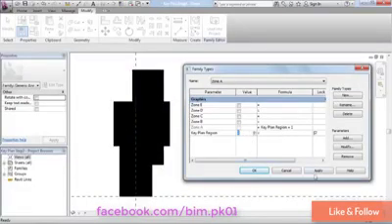So let's see how that works. Let's change this to 1 and click apply, and you'll notice that checks the box. If this value is anything else, right, 0, 2, 3, 4, it's not checked because that condition is false. So when it evaluates this condition, if it turns out to be true, it checks the box. If it turns out to be false, it doesn't check the box.